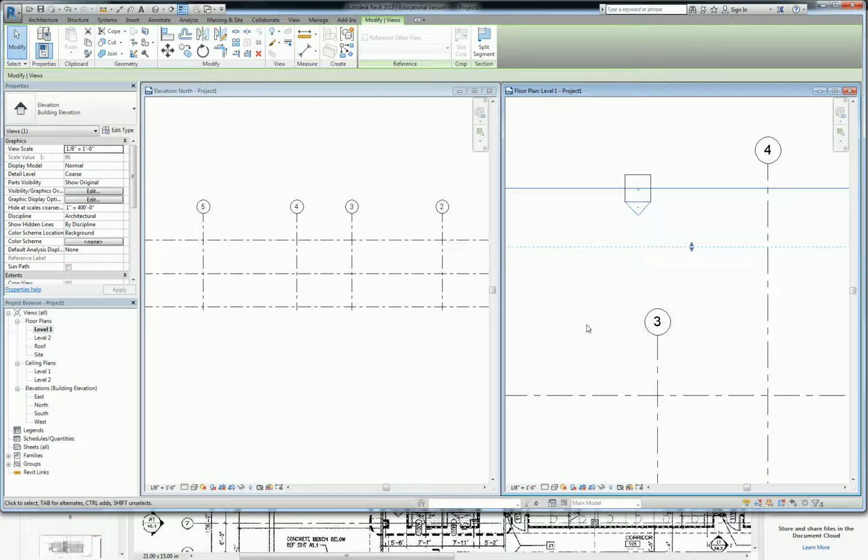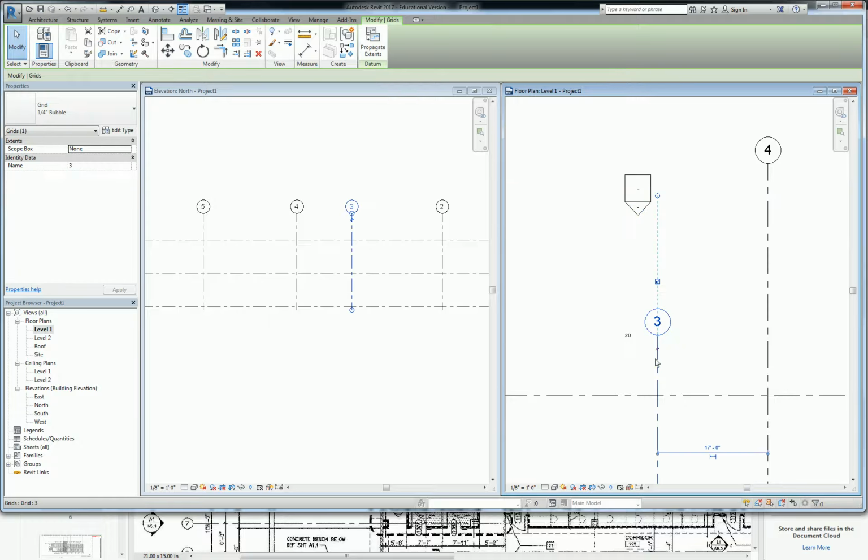It shouldn't be showing an elevation, but it is, because if you select that and you see where that little circle still lies, that's the actual 3-dimensional extents. Does that make sense? That's a feature built into grid lines, so you can modify them on sheet, like when you have a really complex plan and you need to pull this one in because it's sticking off the page. It's a really nifty feature.